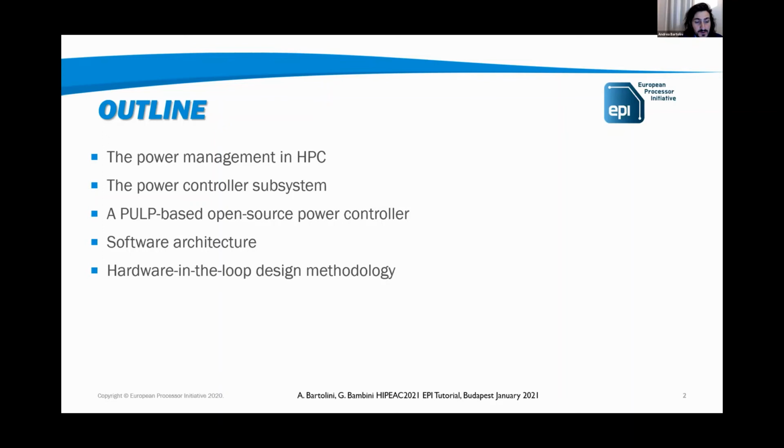Then I will present the power controller subsystem designed in EPI. We will present the fact that it's an open source design, and also the firmware is open source, which means it is based on the PULP-based architecture, which makes it suitable to be open source. We will describe the software architecture and the hardware-in-the-loop design methodology that we are using for testing it and developing it.